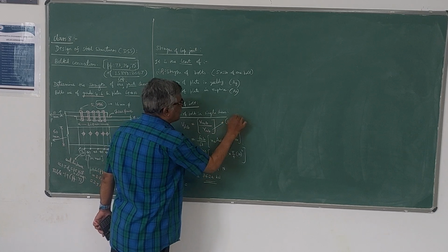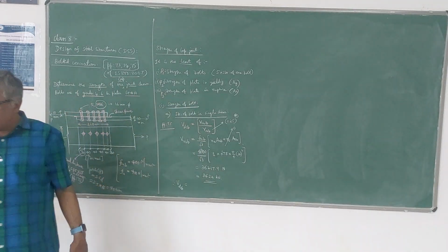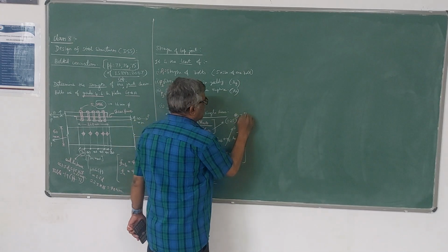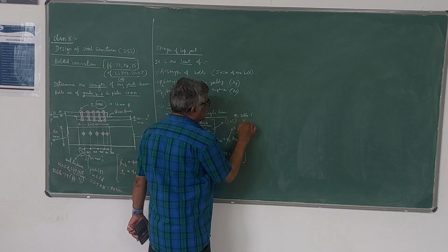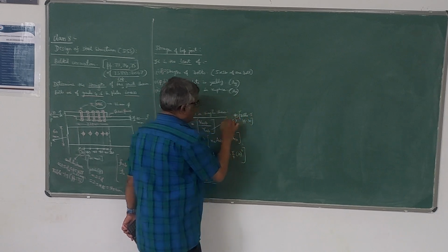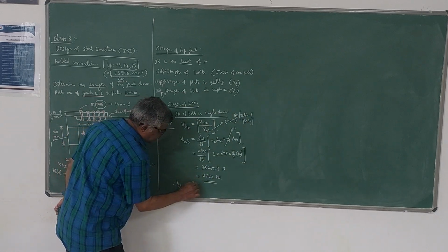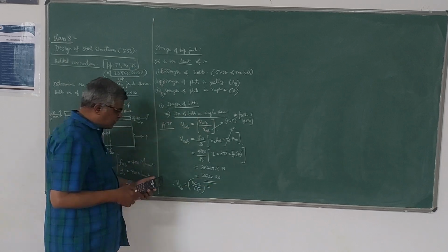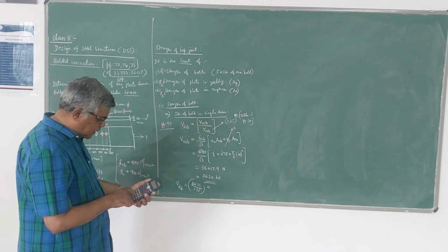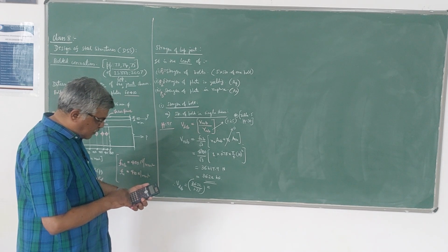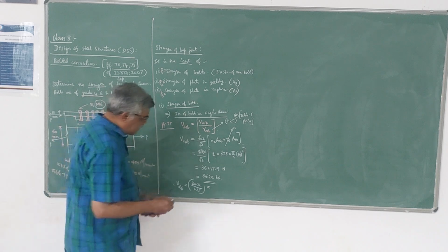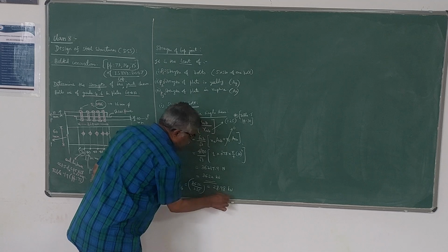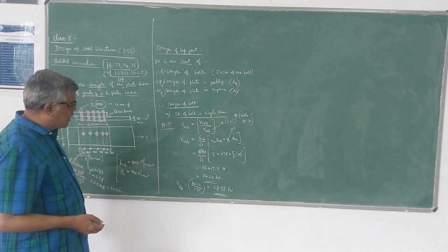Better you remember this. Otherwise, you have to refer to table 5 given in page 30 of the code. So better you remember this table 5, page 30 of the code. This value is available. So therefore, this is 36.22 divided by 1.25. This value is VDSP for the 16 mm diameter bolt. So 36.22 divided by 1.25 is 28.98. You can take it as 28.98 kilonewton. So this is the strength of M16 bolt in single shear.